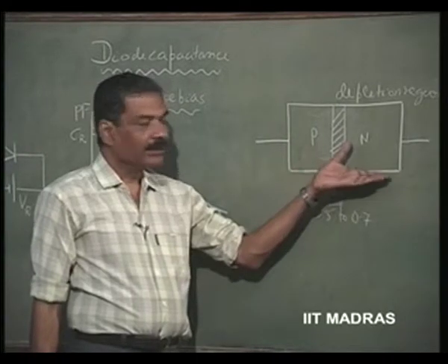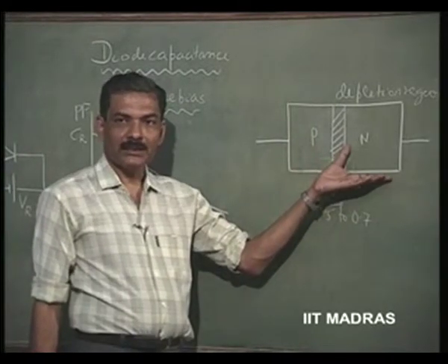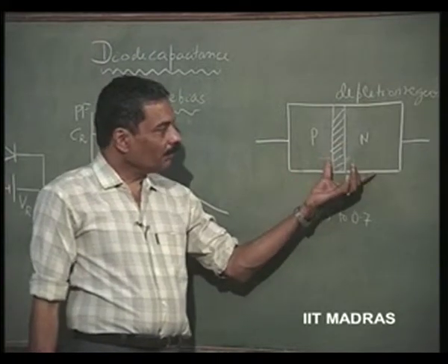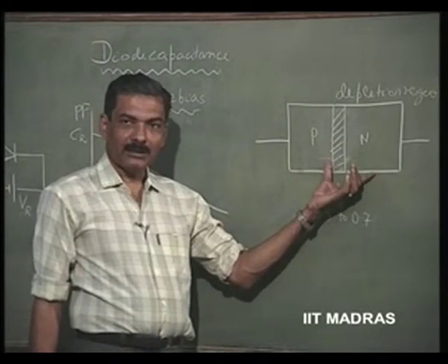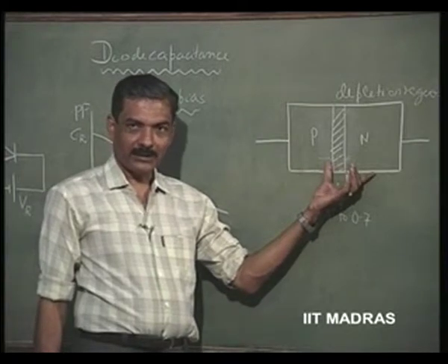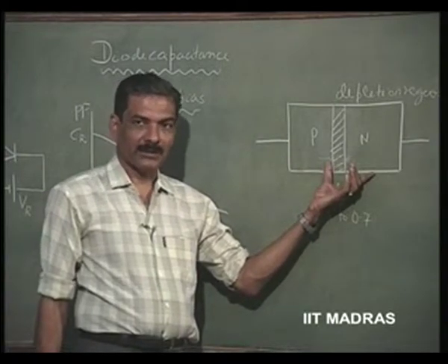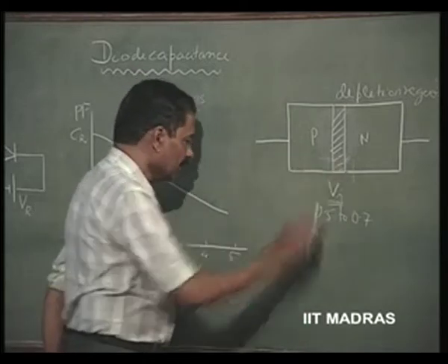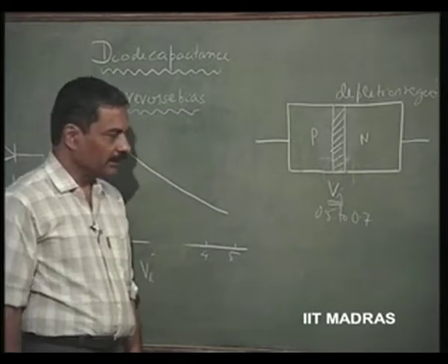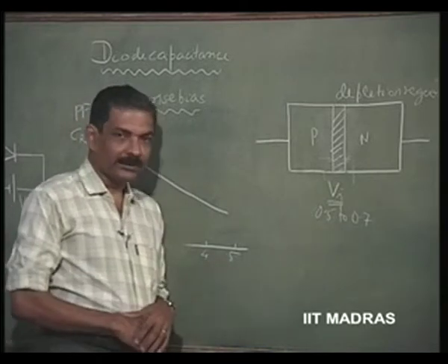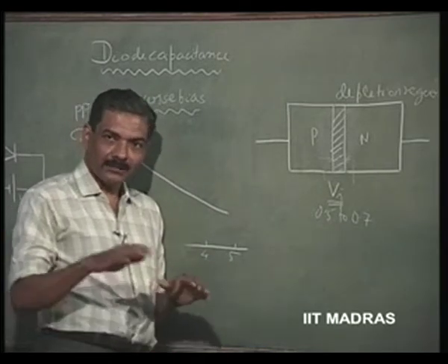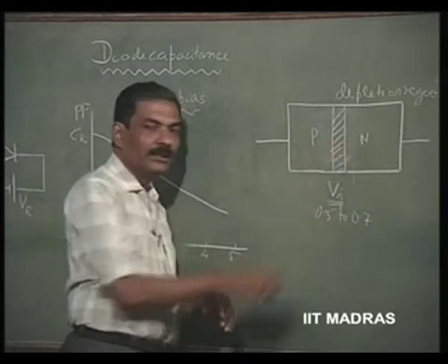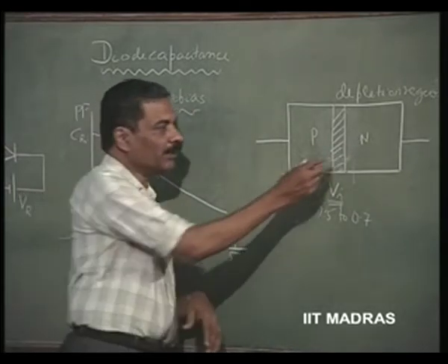That means the reverse resistance is very nearly infinity, but it can be now equated to a capacitance, not just an open circuit, but capacitance really. Therefore, we can always say that a junction diode under reverse bias condition, apart from being considered DC wise carrying only the reverse current, can be also constituted to have a capacitance which is dependent upon this.